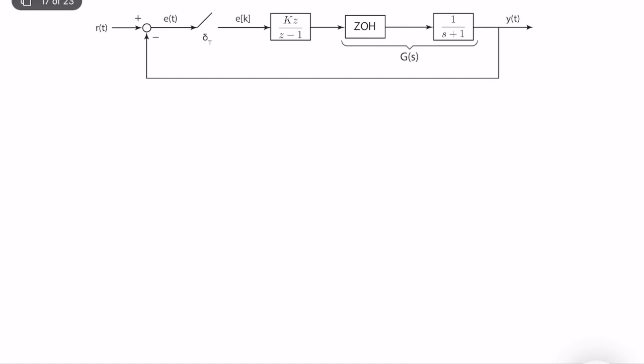In this video lecture, I will analyze Root-Locus behavior of a digital control system under different sampling time conditions. We have a plant, which is a simple first order plant, 1 over s plus 1, with a zero-order hold. And we have a controller, which is a PI controller, not technically a nice controller, but we are analyzing from the perspective of Root-Locus anyway.